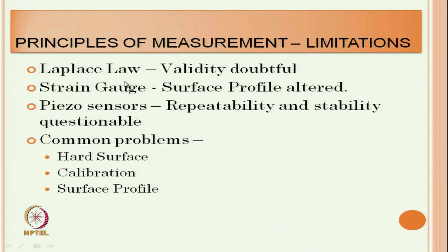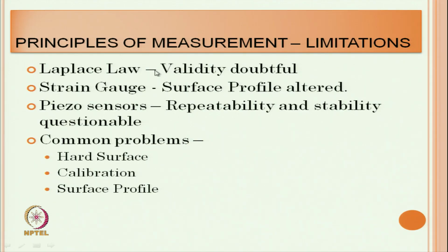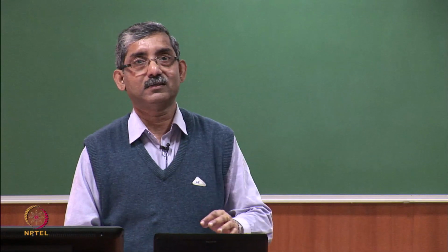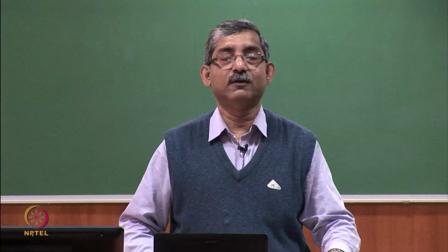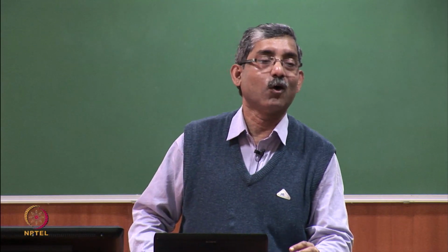Laplace law is one of the basic equations from which we can get an idea about the pressure applied by the compression bandage, but the problem here is that its validity is doubtful, because the actual pressure, when we measure it using different sensors, is different from the calculated pressure which we get from the Laplace law.